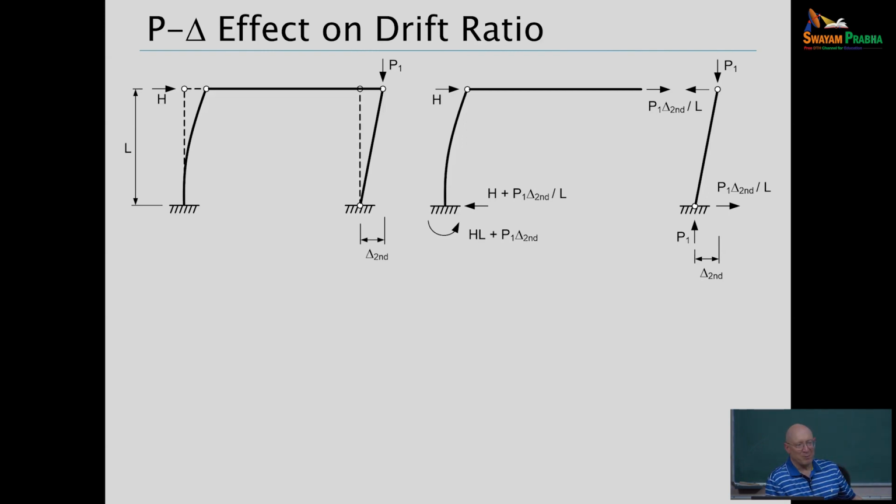Okay, very nice, but we haven't figured out what delta second is yet. And that's the nature of geometric nonlinear analysis: the delta second depends on the loading, but the second order effects depend on delta second. And so generally we have a nonlinear problem. A few definitions here. I thought of taking these out, but then I left them.